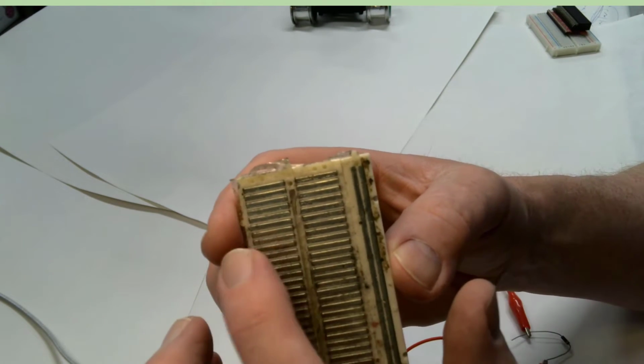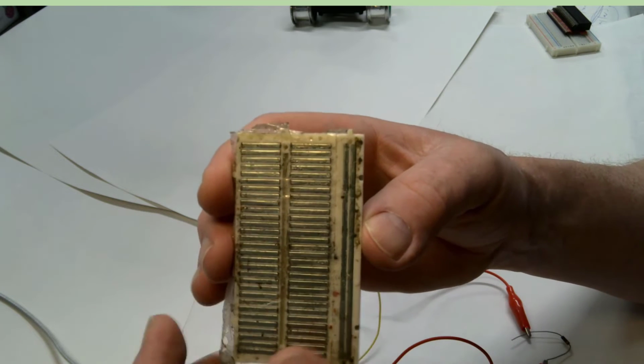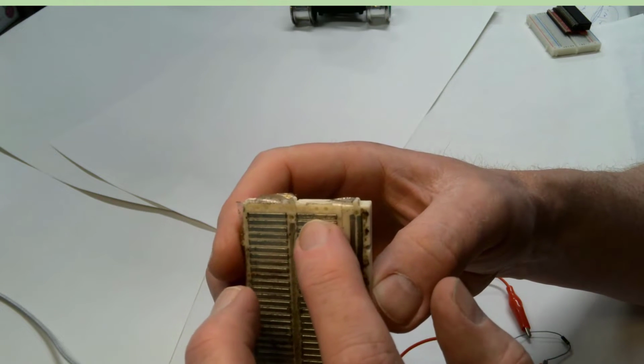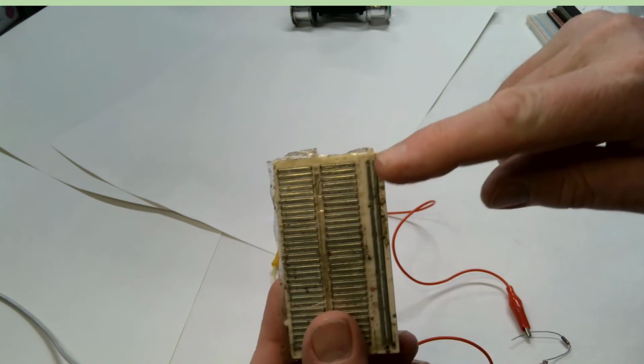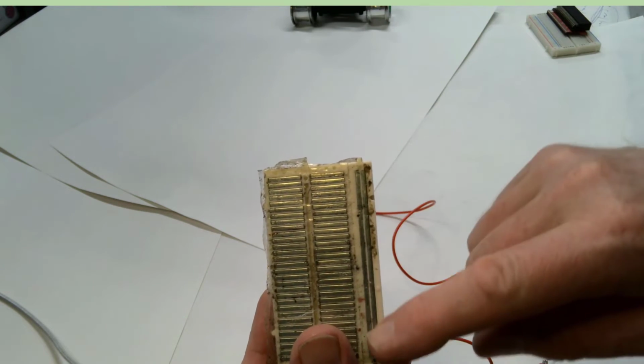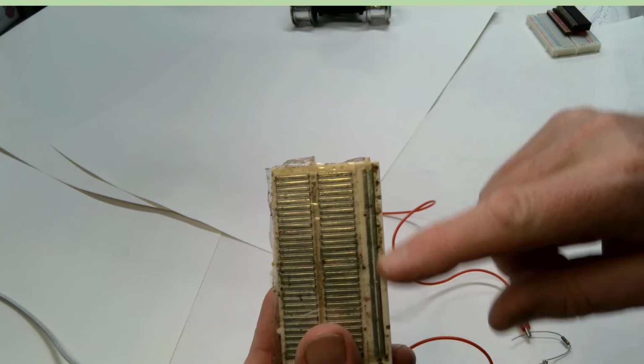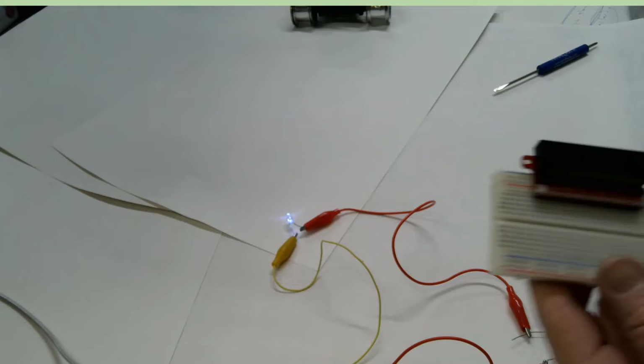There's the little metal strips. They don't connect together from side to side, but any of the little holes on the other side of the breadboard, if I plug in there, they're electrically connected together, and all the holes along those side strips, which are called the rails, are electrically connected.